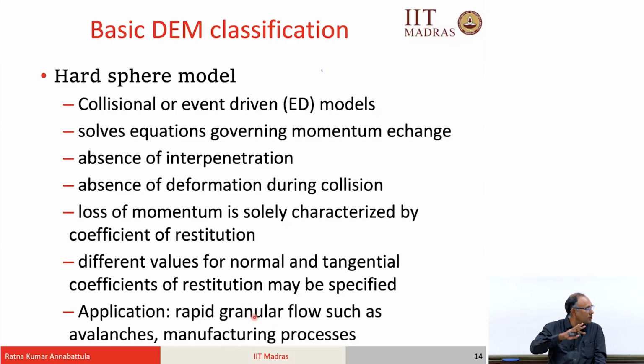the non-linearity of these contact force interactions takes a lot of time. So, when you are not interested in what is happening to the deformation of individual particles, it is not recommended to use the soft sphere approach, particularly for large scale granular flows such as avalanches and manufacturing processes. Probably we can resort to the hard sphere model, which is simply considering momentum exchange.